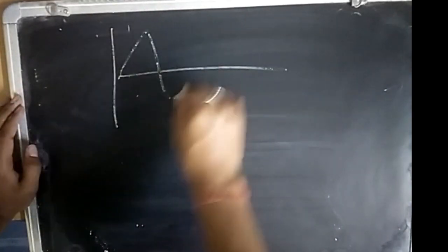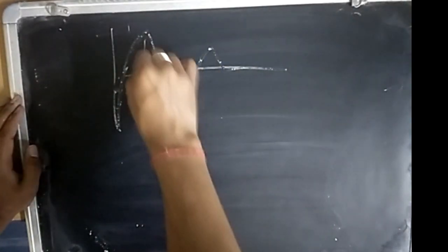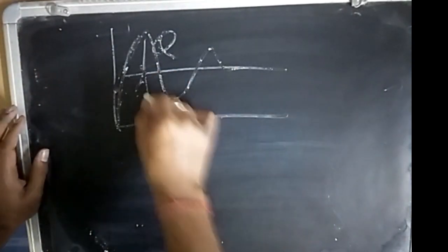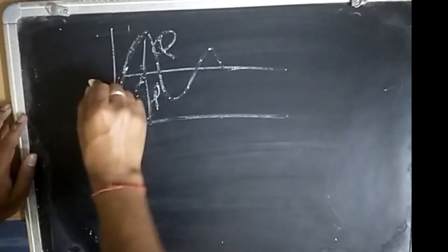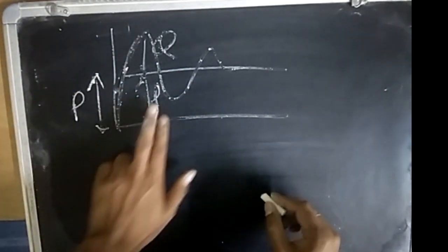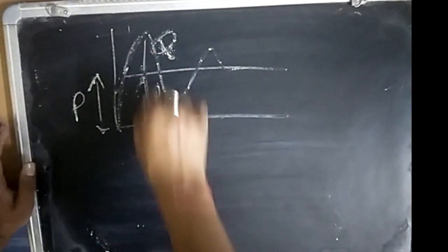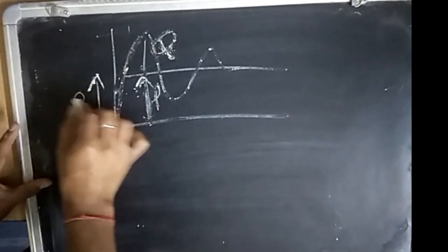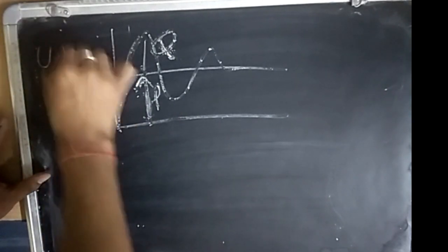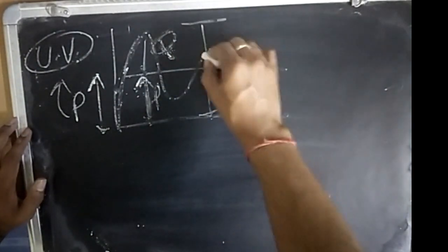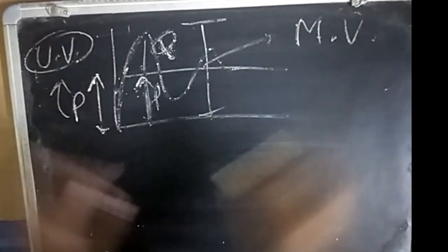And similarly, let me draw it over here. This is my, let's say, Q, this peak, this is my overshoot, and from the bottom it is P. I really want to reach my P distance only, but due to the underdampedness, the oscillations are there. So this P is my aim, my ultimate value, but the maximum value that I can reach is P plus Q.